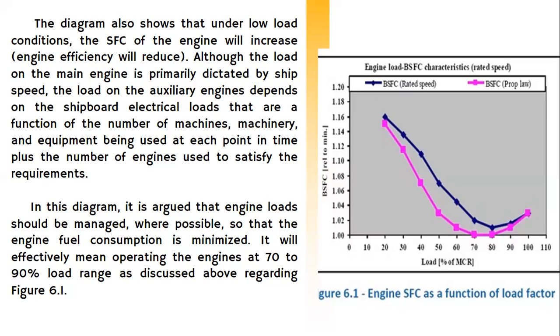In the diagram, it is argued that the engine load should be managed where possible so that the engine fuel consumption is minimized. This effectively means operating the engine at the 70 to 90% load range, as discussed above, where possible.